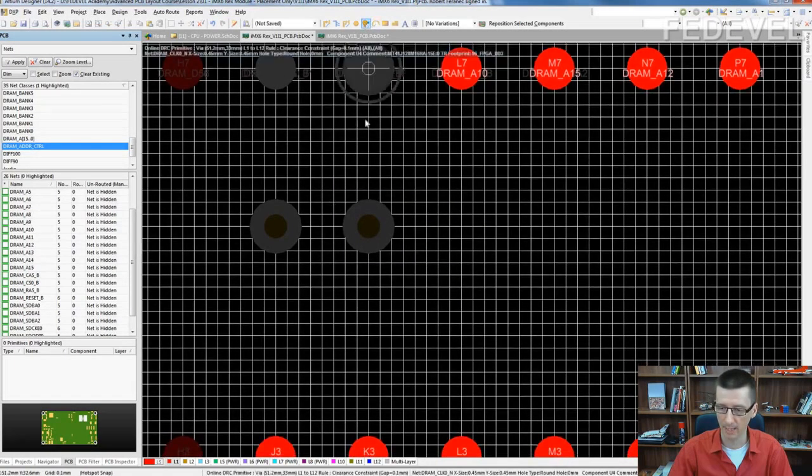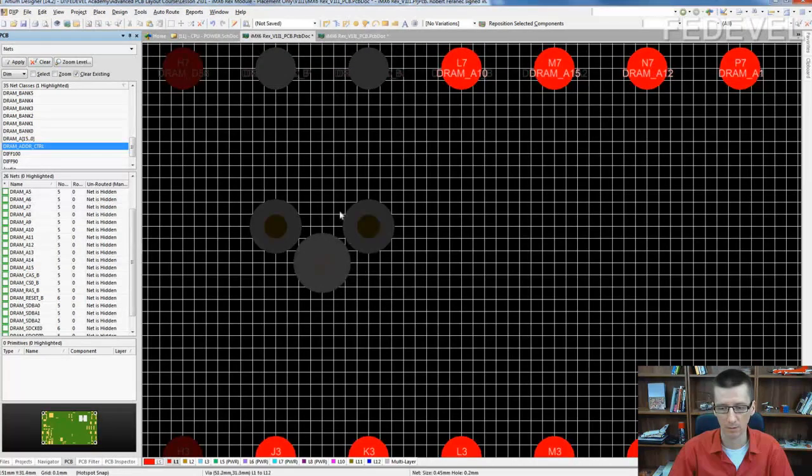What about this other row? Shall I place it here? Here? Here? What is the difference if I place the through-hole via here and if I place it here? You need to be careful and think about the power planes and ground planes. If you place through-hole vias very close, there will be no space for copper to flow between them.